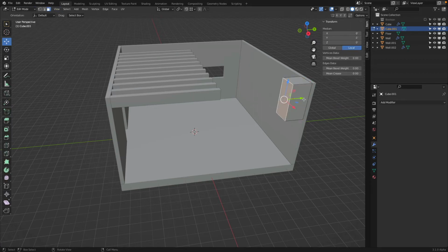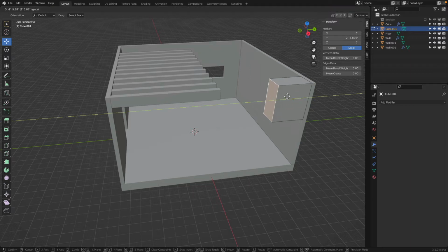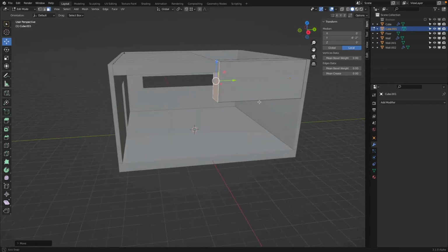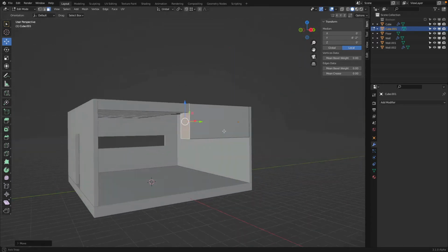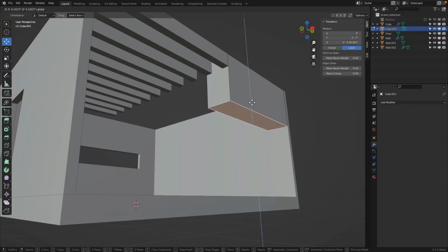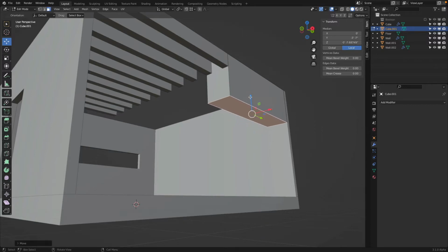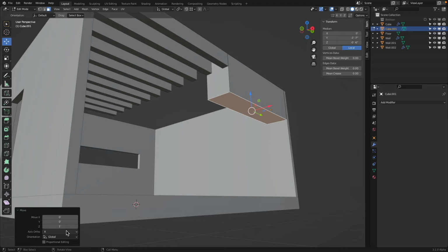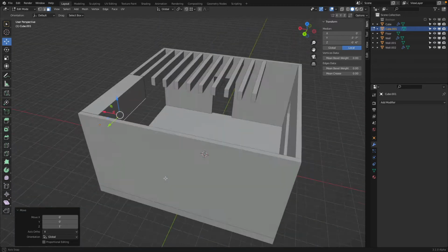So for mesh modeling, edit mode, move this face. So we slide along Y, hold control and release. Yeah, this is maybe a tick too deep. I would like to move this one up by 1 foot. When I move this one up, look at this. Oh, okay. Z, move this by 1 foot. So I can work very precisely.